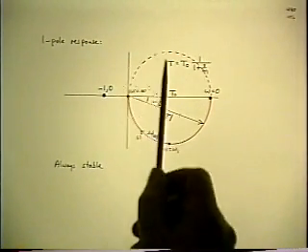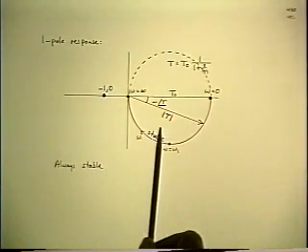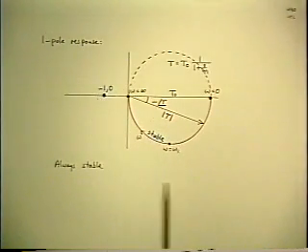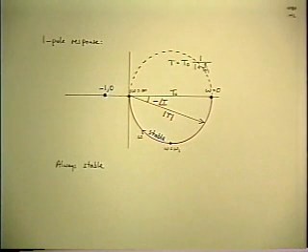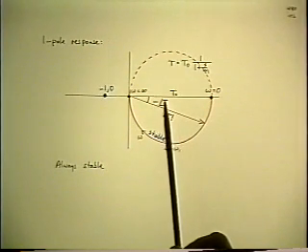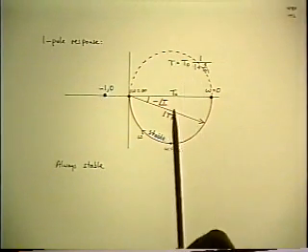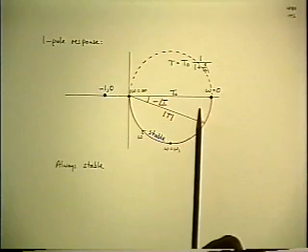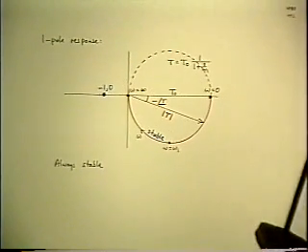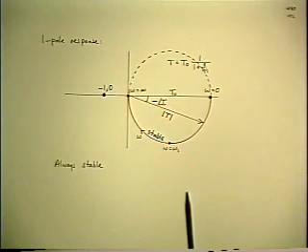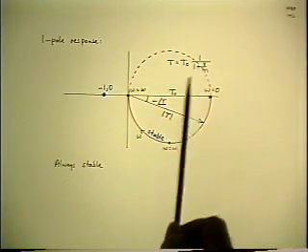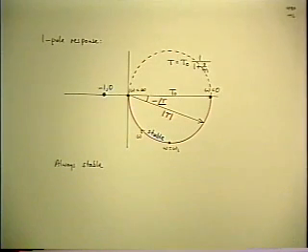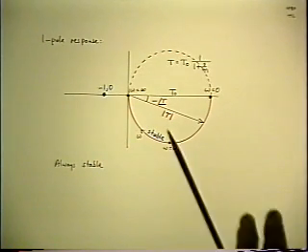So the Nyquist criterion says that the closed contour must not encircle the -1 point. And so when you look at this result, the answer is it does not encircle the -1 point, and moreover, it never will, regardless of the values of the parameters. Because changing t0 or omega 1 simply changes the scale of the circle, but it will always remain on the right-hand side of the origin, and it will never get to -1. So the conclusion is a single-pole loop gain is always stable.